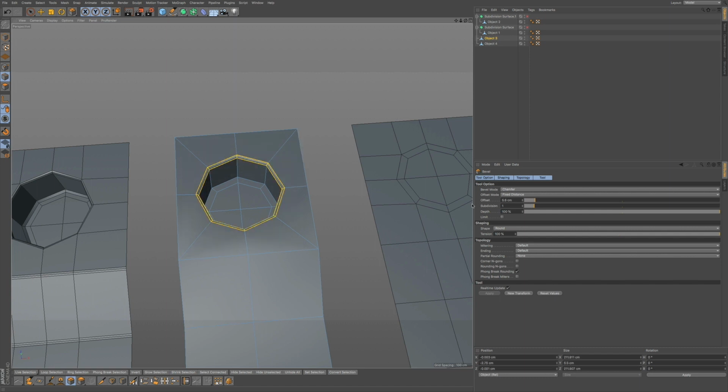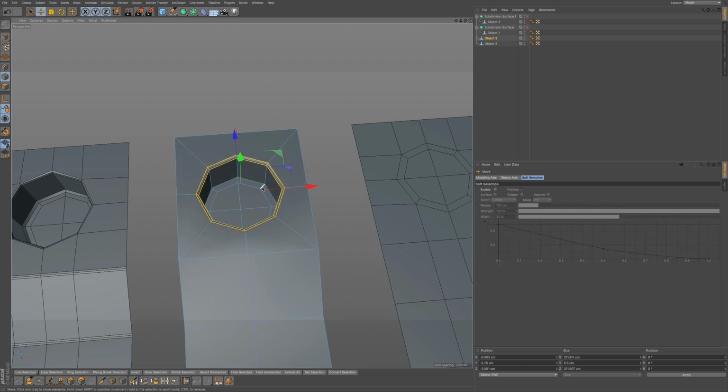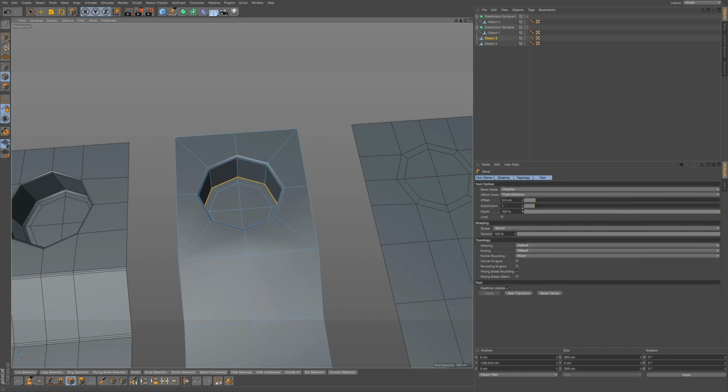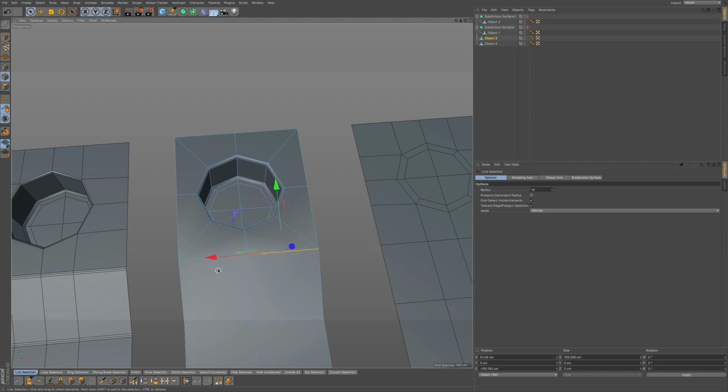Make sure we have one subdivision. E, double click, MS, 0 subdivisions. We're going to have that, so that'll be a nice tight crease. But you know what's going to happen when we add in this bevel here, we're going to have this issue in these corners.